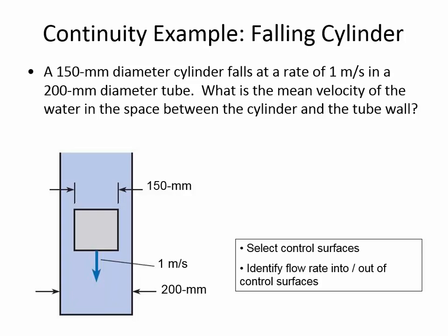And with the flow rate variation, there's a handle on the bench. It's a black handle, and you can turn the jet up and down. You'll set some jet velocity, and then you're going to find out what sort of force is generated. When the fluid jet hits this piece, it pushes it up.